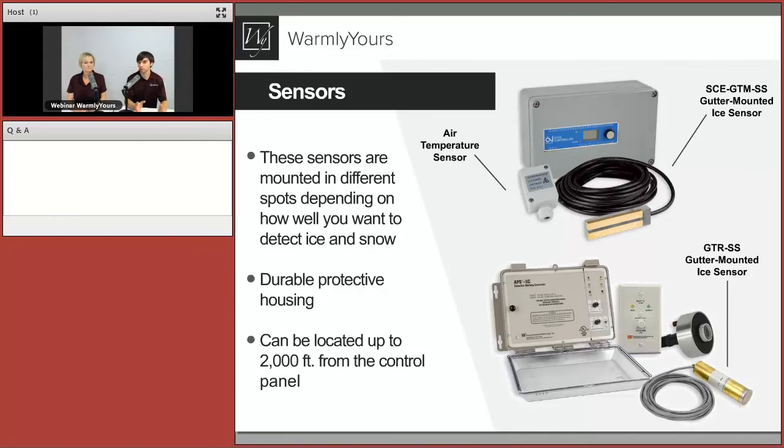In other words, your gutter may not even be receiving snow yet because the gutter is more shielded and covered, while that aerial sensor will be positioned vertically. It will pick up the first snowfall and turn the system on ahead of time. You can always use a combination of the aerial sensor and the gutter sensor for the most reliable control from two different points.